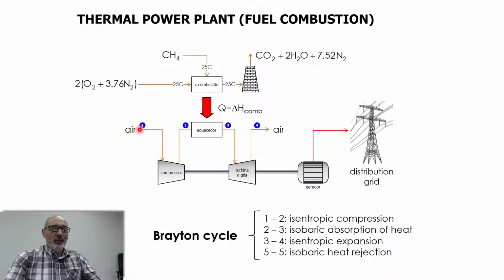Between 1 and 2, we're going to assume that it is an isentropic compression. Isentropic meaning that there's no heat exchange, so it's adiabatic, and there's also no internal friction and no other types of irreversibilities.